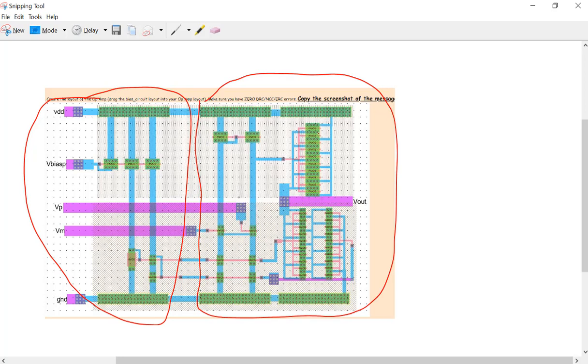You know that the gain stage has large transistors. So these guys are actually multiple transistors being combined together to make up that large one. The way to understand it is, the width right here is 220. It's not 22. So this is a 22 by 2, right? So we are not changing the length. We just want to make 10 times the width of the regular PMOS over here in the previous stage.